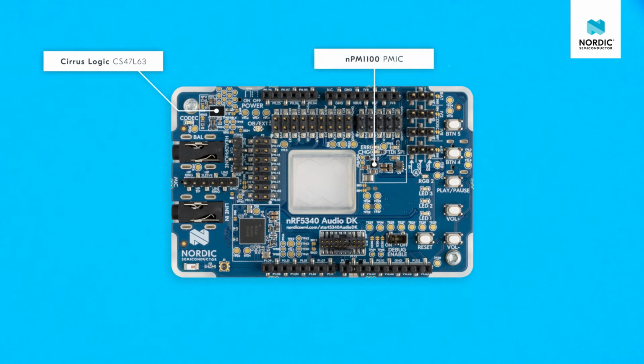The power management and battery charging are handled by our nPM1100 power management IC. It is a super small, highly efficient PMIC for charging batteries and power delivery. Its power conversion efficiency goes up to 92% with a footprint of only 27 square millimeters. This includes all the passive components. You can even get as small as 23 square millimeters for size-constrained applications.